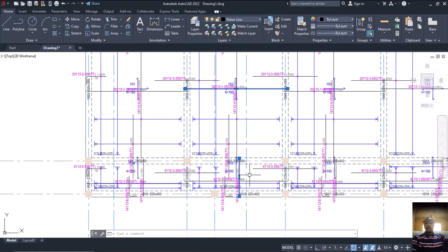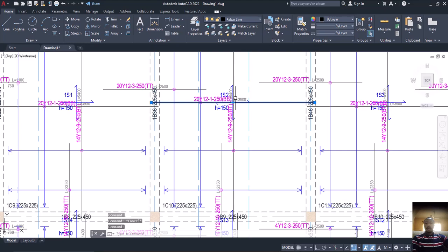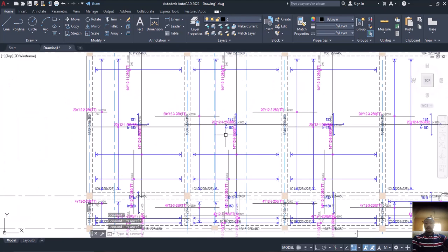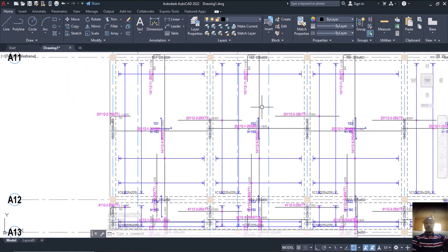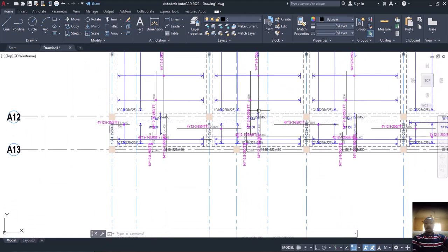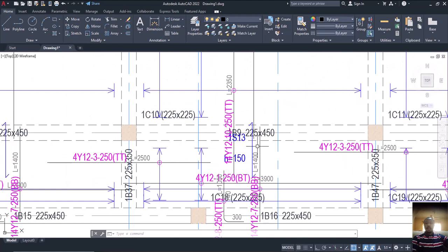Now it's very simple. Let me also dash that one out. Now, this is the main reinforcement, bottom. Why is this one what? Distribution bar. Am I correct? This one is the distribution bar. And if you look at the main reinforcement, it spans along the short distance. This is BB, bottom reinforcement. Can you see it now? It spans along the short distance, while the distribution is along the long distance.